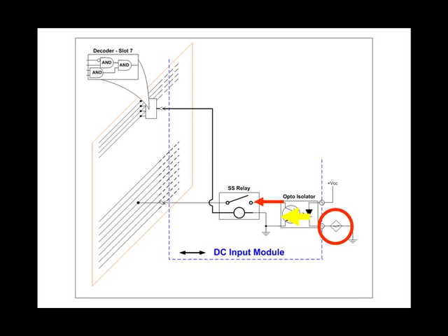When slot 7 comes up, a binary 7, that's 0, 1, 1, 1, is sent down the control bus, activating slot 7, and all 16 solid-state relays are energized together, placing the state of each input device directly on the backplane. The processor transfers the state of the 16 conductors of the backplane into a word in memory set aside just for the inputs of slot 7. Remember, that was word I:7.0.